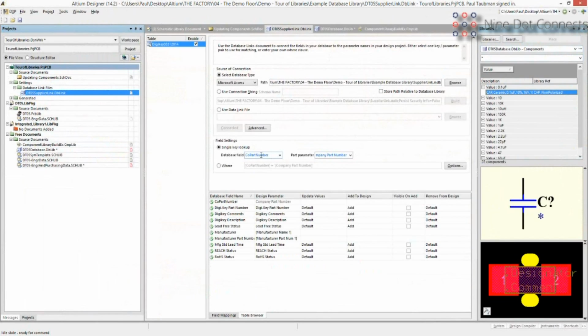That's why it's really important to have a unique ID, and these unique IDs have to match up with each other. So going back to that comment I made about the company part number, you're like, why is he fussing over that? The reason is that the part number has to not only exist in your database library, it's got to ultimately exist in the PLM, and that's how they're going to match up with each other later on. In my case, my key field is the co-part number.